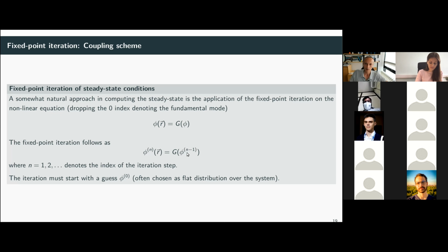So basically that means that you would use that flux as the input of the thermohydraulic solver to get the temperature field, the T infinity, and then you would use the T infinity to model the conditions in the reactor, and you would calculate the flux phi 1, right? And you would use the phi 1 flux in the next iteration step as the input for the G function. And then you would repeat these steps over and over until hopefully you would converge the system.